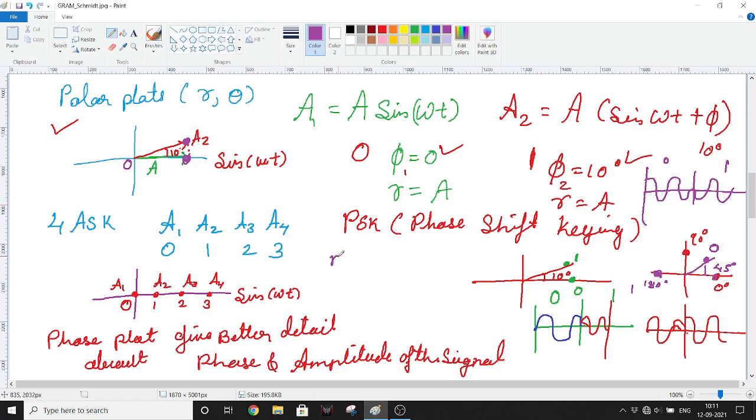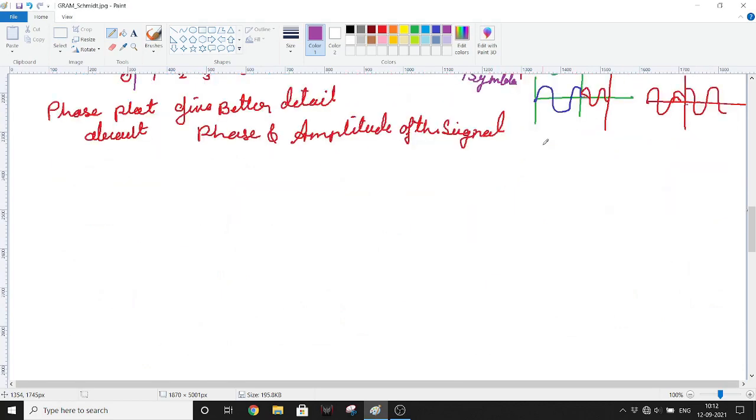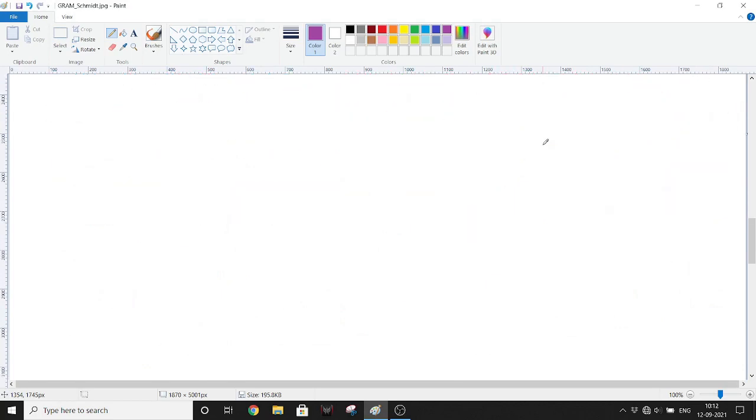The same thing goes again. M-ary PSK can be represented with multiple symbols at the same time. Again here M is equal to 2 raised to n, and n is the number of bits grouping, bits per symbol. Okay, let's have a look at an example, a 4 PSK.